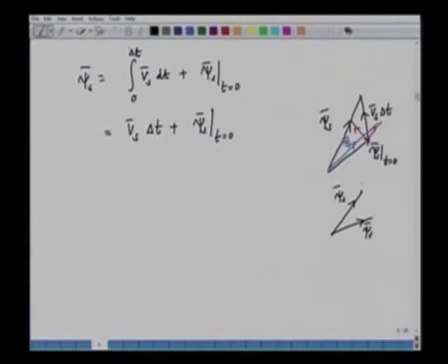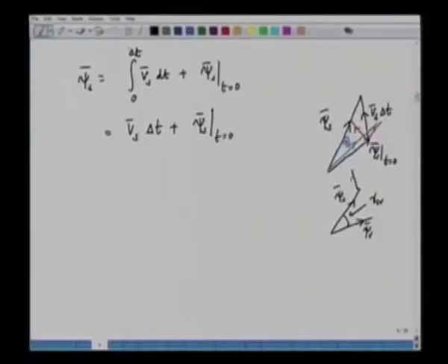and we are able to control the stator flux instantaneously by applying a suitable voltage vector. So, we can increase or decrease this angle gamma SR, depending upon how we control the stator flux. This angle is gamma SR. If you want to increase this gamma SR, you have to apply a voltage vector so that the angle is increased further. If you want to decrease this angle, you can take another situation where the angle is reduced.